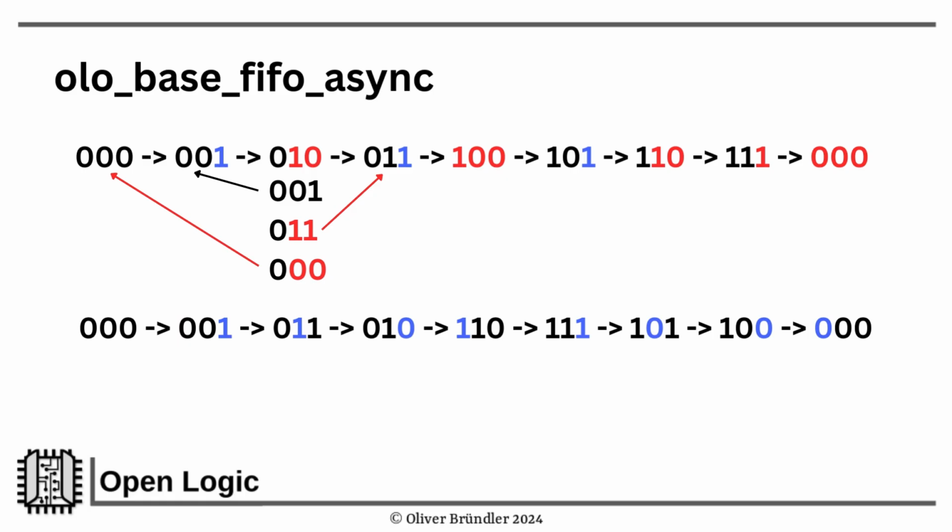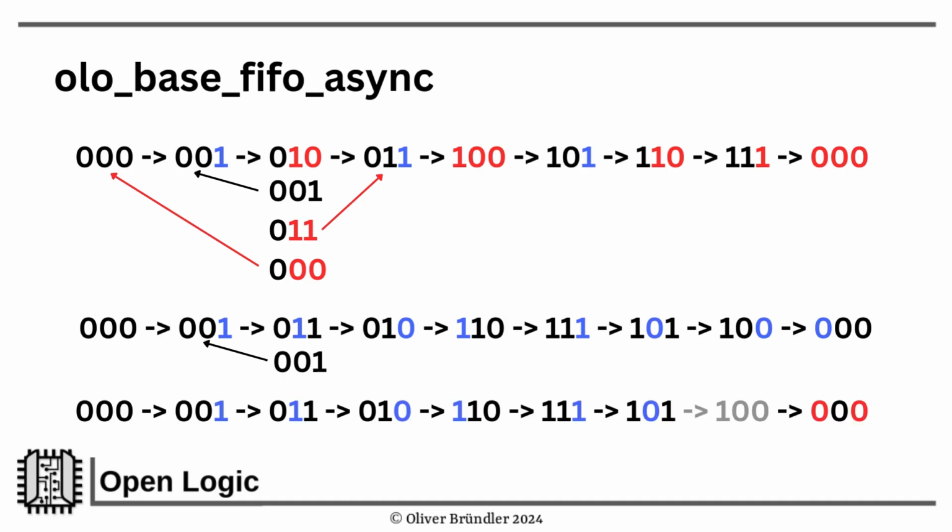Gray coding ensures that from one counter value to the next, only one bit toggles. So worst case, we see the last counter value and not something else. However, this concept only works if the wraparound of the counter is at the power of 2. Otherwise, we would have multiple bits toggling around the wraparound, which would be unsafe, for exactly the same reasons as binary counters being unsafe: multiple bits toggle. Therefore, the asynchronous FIFO comes with the limitation that the depth of the FIFO must be a power of 2.